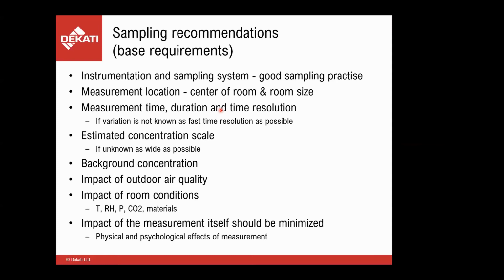The standard sets base requirements, what you should always do when you are doing measurements according to this standard. Of course, good sampling practice should be used to avoid particle losses in any of your sampling lines. Measurement location, if no other consideration applies, should be at the center of the room. And if it's a really small place, like a closet, you can't take more than 10% of the room volume as sampling flow per hour.